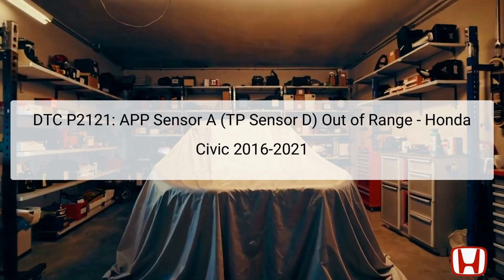DTC P2121 pertains to the APP sensor A, specifically referred to as TP sensor D, which indicates that there is an issue with the accelerator pedal position sensor's performance or output. This code is triggered when the sensor's readings are outside the expected range, which can impede the vehicle's acceleration and overall performance. The APP sensor is located at the accelerator pedal assembly, detecting how much the pedal is pressed and sending that information to the engine control module, ECM, to adjust engine parameters for throttle control.